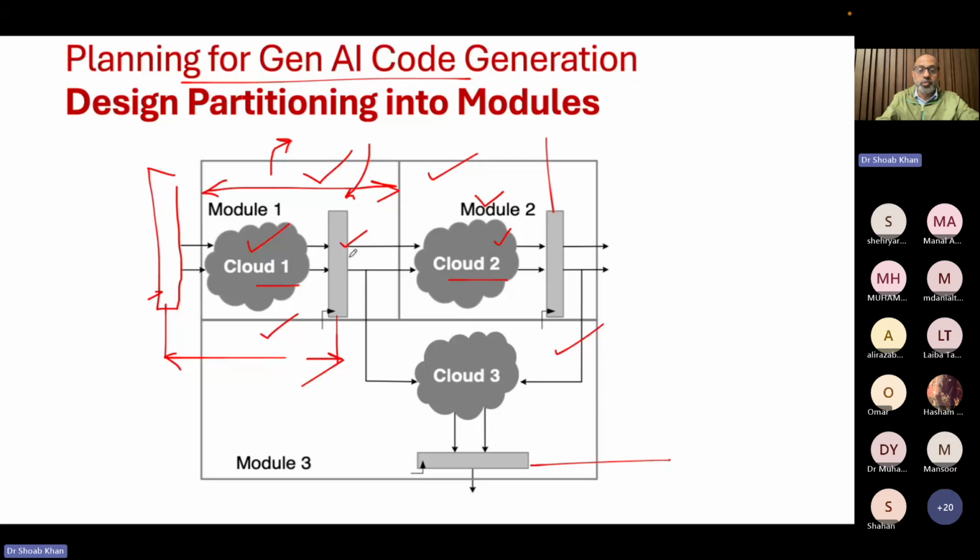If the algorithm assumes the same value to be used by the computation which is happening here, a register would add a delay. So a register would make the algorithm use the previous value. So everything will be changed and you will not get correct results. Please remember, a register is usually an algorithmic entity which makes a piece of functionality use previous values of your results. If this is not what you mean, then adding a register is not that simple.